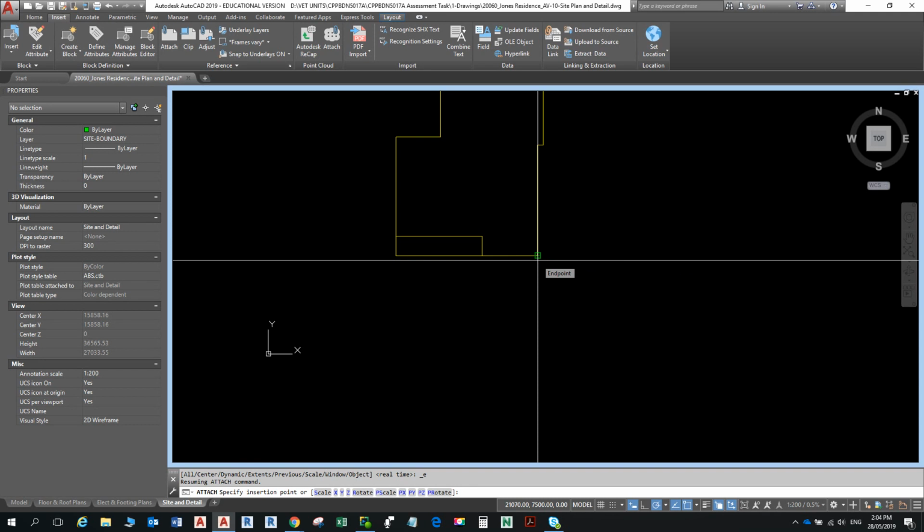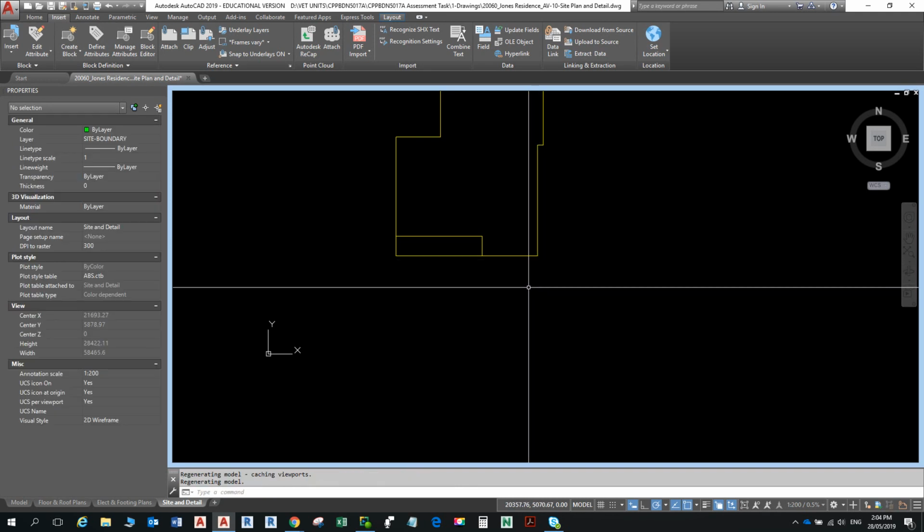for now. It's not the right location, but surveyors have the habit of drawing the site at the exact coordinate location, as you can imagine, GPS location, where the site exists on the Earth. So their coordinate system is absolute coordinates from 0, 0. Us designers just open the drawing and start drawing anywhere.